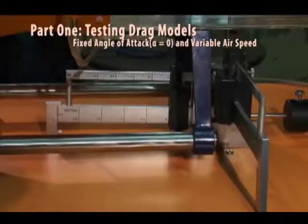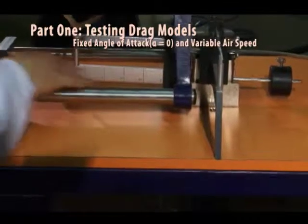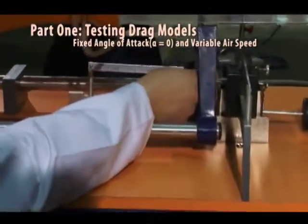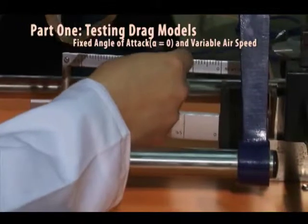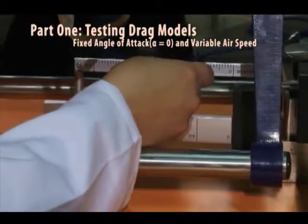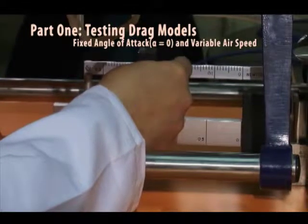The drag force exerted on the model will move the model from its original null position. The drag force can be obtained directly in newtons using the two-component balance. The drag force can be read directly using the balance by moving one or both masses on the balance.